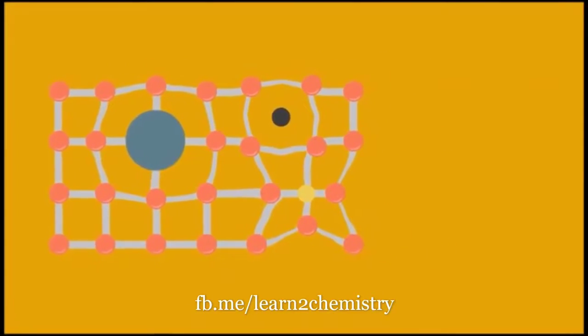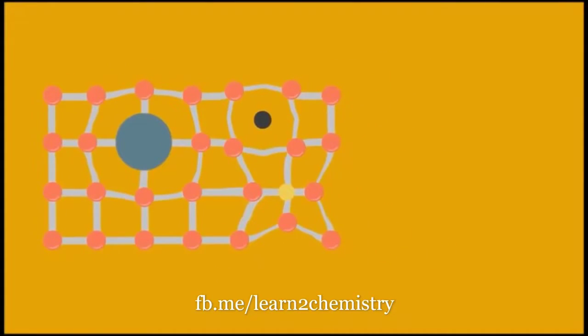The smallest elements, like carbon, lay in between the iron atoms. These are called interstitial. We have the largest atoms which replace an iron atom, like molybdenum. This is called substitutional. This type expands the structure. Or we can have smaller substitutional atoms, like nickel, that collapse the structure.